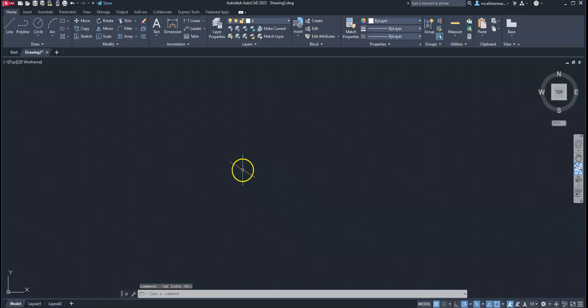What that has done is it has changed it so our cursor is now on a left side plane. What I mean by that is the cursor would sketch, let's say, if this was a window, only on this side. Now if we wanted to flip that, we can go to ISO top, and you're going to see the grid now changes to where I'm only on top of the surface. If this was a cube, we can also switch it to ISO plane right, and it will be on the side.